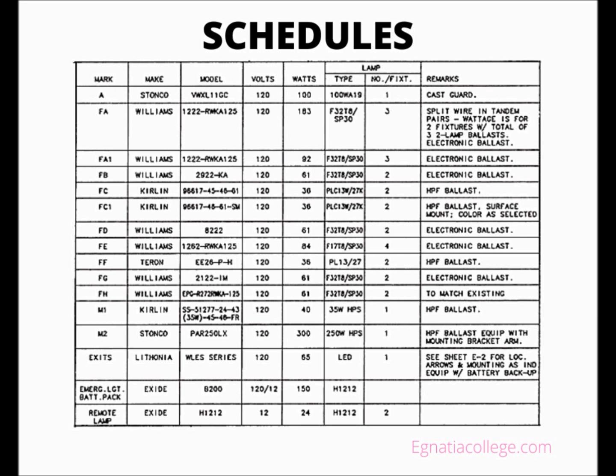When a commercial project has a kitchen, you should have a kitchen equipment schedule. If the drawings do not have one, it is very helpful to make one for the installer. The kitchen equipment schedule should include equipment number or designation, description of each equipment item, the load in horsepower or kilowatts, volts, wire size, conduit size, protection in amperes, who will furnish each equipment item, furnished by others or by contractor. Installation requirements. Remarks column for any detailed specific information required.